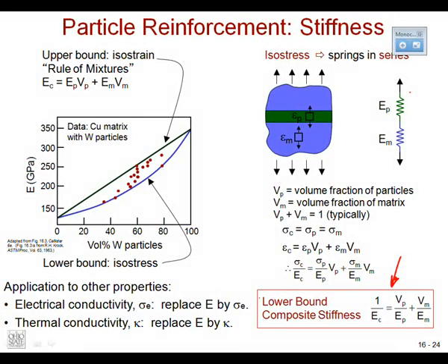And so what we find, here's modulus versus volume percent. This is the upper bound. The green is the best we could get in terms of stiffness, and blue is the worst that we get in terms of stiffness. And so the composite, if you check the stiffness in all these different directions, will lie within that envelope, because, of course, we don't always get them completely aligned longitudinally.